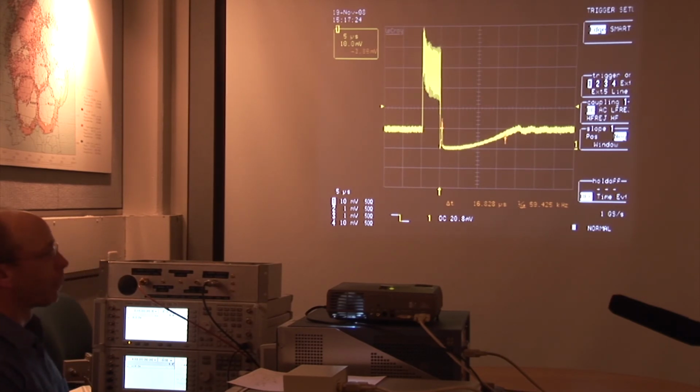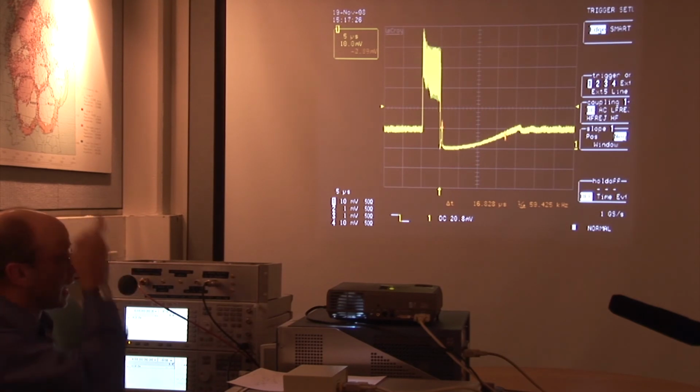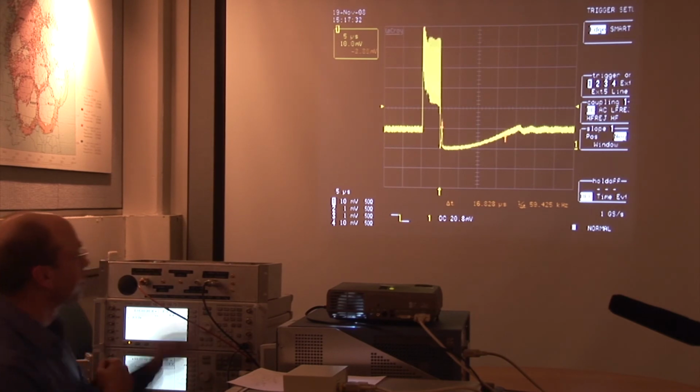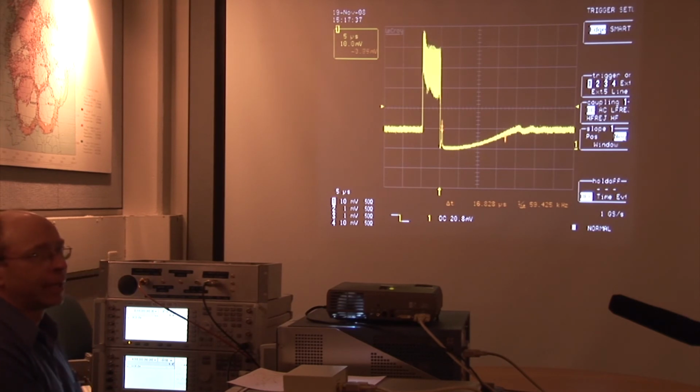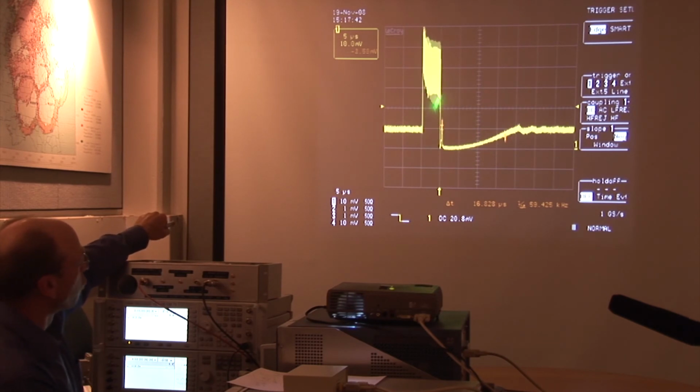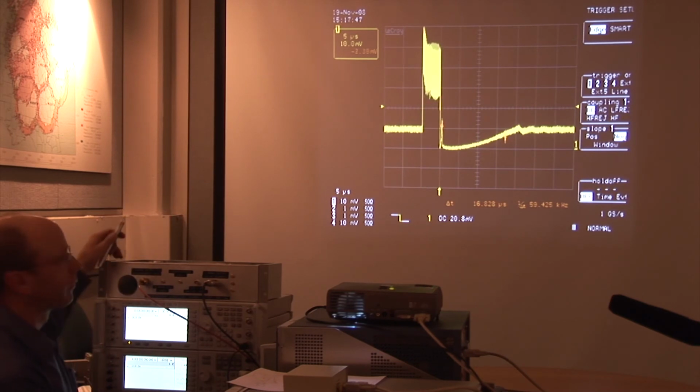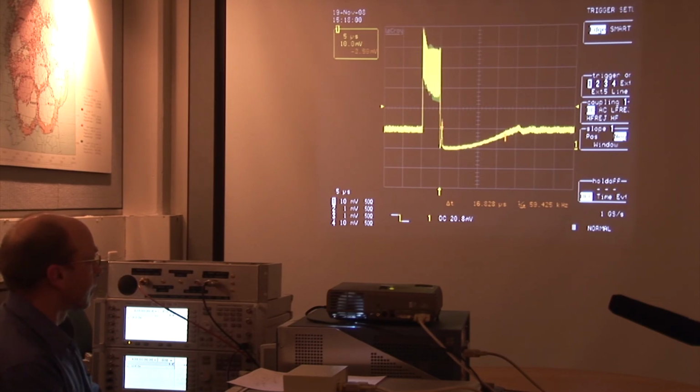You know it's not going to be a low-powered source in all likelihood. In the talk that I'll do next time, I will describe a pathological situation where you can see this occur even if you do have a bandpass filter on the front end of the receiver. But suffice to say that in normal situations, if you see this happening, the only possible solution is to put a filter on the front end of the receiver. There's no mitigation that can be undertaken with the transmitter short of literally turning the transmitter off. That concludes the whiteboard talk and the lab portion.